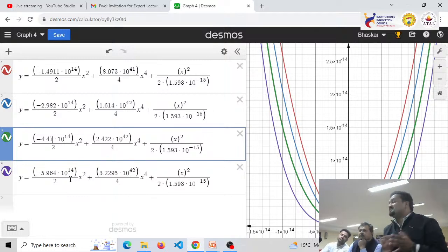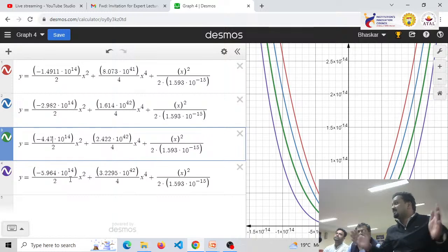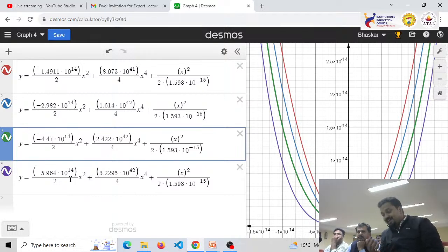This explains that there is something called negative capacitance present over here. That is why the total capacitance has enhanced. Otherwise this is not possible in normal positive capacitance. There were two ways through which I can confirm the presence of negative capacitance. One was capacitance, and the second was voltage drop. In these two curves, I have focused on how the capacitance is getting increased. Here the curve is flatter, so capacitance is more. And in the previous one, because the slope of the charge versus voltage characteristic for TFE equals 120 nanometer was higher, I can say the capacitance is higher.